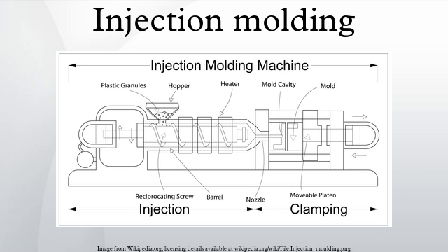Accordingly, the screw reciprocates and acquires material for the next cycle while the material within the mold cools so that it can be ejected and be dimensionally stable. This cooling duration is dramatically reduced by the use of cooling lines circulating water or oil from a thermolator. Once the required temperature has been achieved, the mold opens and an array of pins, sleeves, strippers, etc. are driven forward to demold the article. Then, the mold closes and the process is repeated.